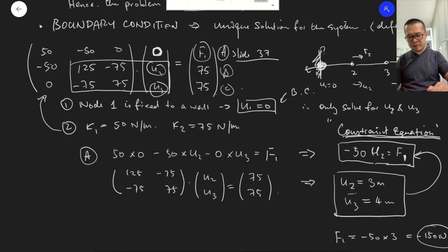By giving some boundary conditions, for example, the specific loading on particular nodes, or whether some nodes in the structure are fixed, we'll be able to start solving these equations to get a set of unique solutions that will tell me, for example, the displacement or deformation on specific nodes. So these are the primary nodal quantities that we are interested in.